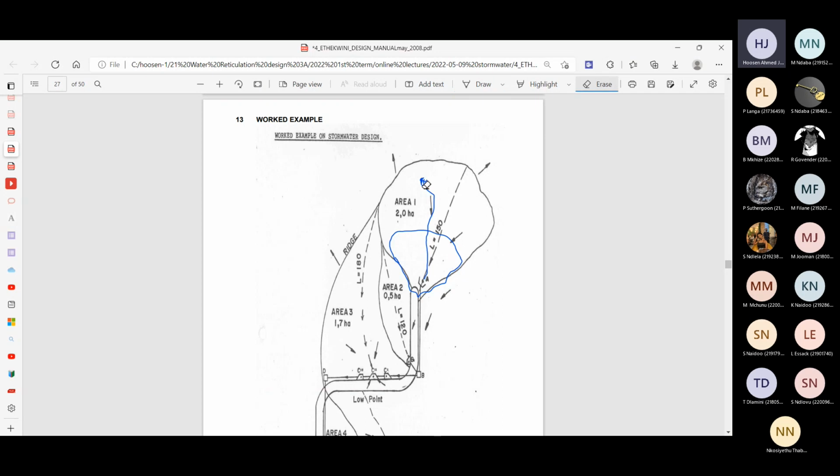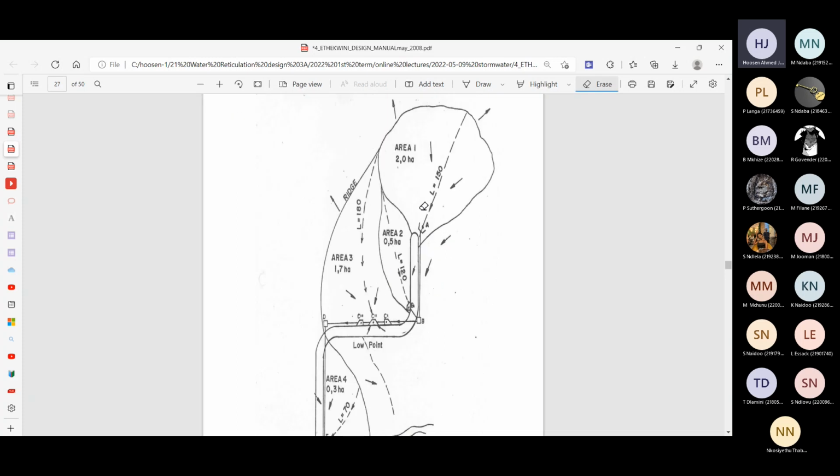So it's important for you to identify the ridge lines or the highest points, and once you've done that, you can then mark up your actual catchment areas. And I'll stress that you don't have a discretion in deciding these catchments, the extent of it or the size of the catchment area. And that's how it is in nature when you go out there.